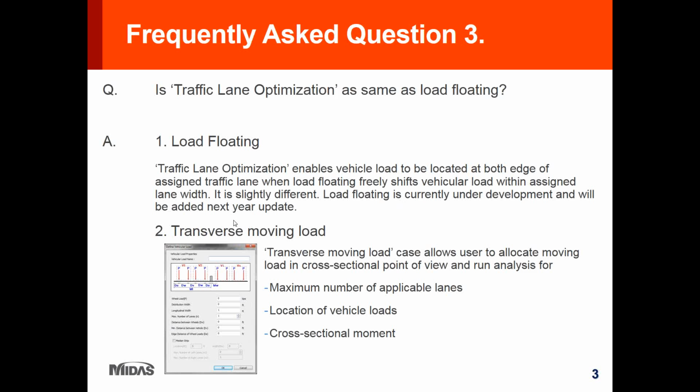I defined this transverse moving load at the support at the pier caps, and then ran the analysis and retrieved the result based on the critical element from the dead load analysis, meaning the moving load location is based on the critical element of the dead load analysis.